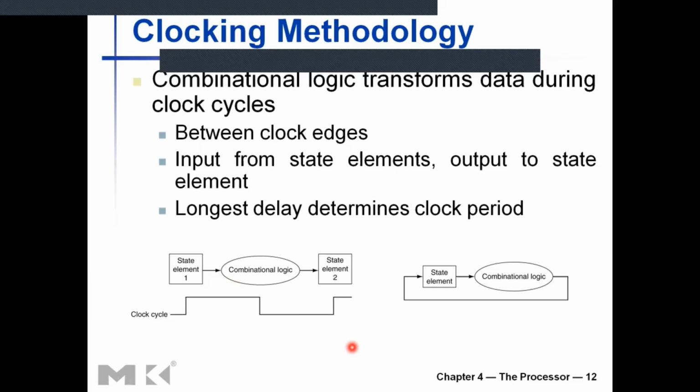Right. So in our initial design of the MIPS processor, we will implement a single cycle processor. That means an instruction will take a single clock cycle to complete, and all instructions are able to complete within that clock cycle. That is the idea of a single clock cycle. Every clock cycle you need to be able to complete one instruction.